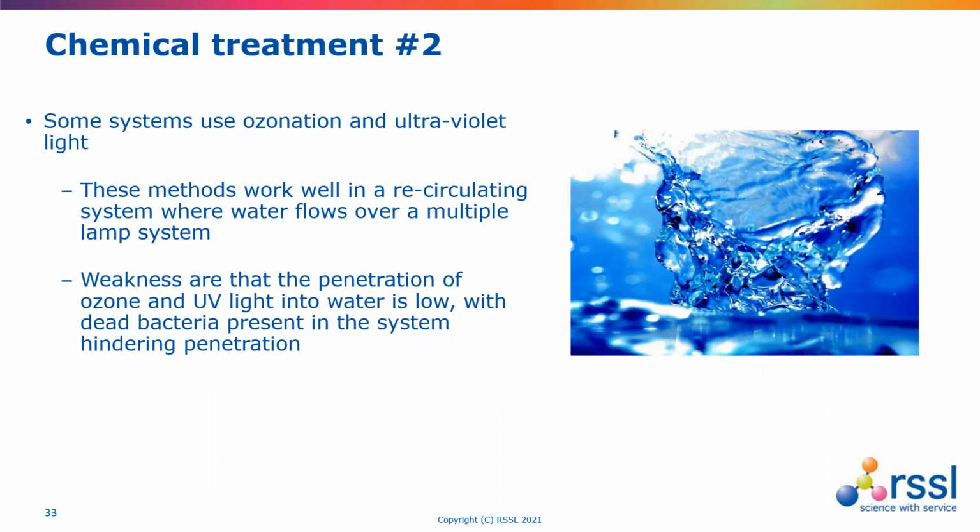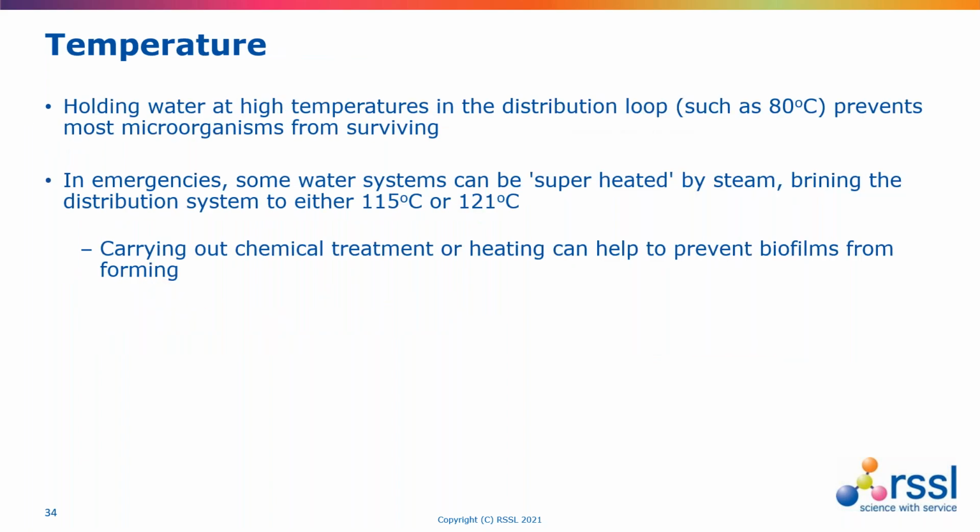With purified water systems, then ozonation tends to be the most common method, normally then using ultraviolet radiation to break up the ozone to make it suitable again after the ozonation process has happened. To a degree, UV light can disinfect, but getting the contact time sufficient can be challenging.